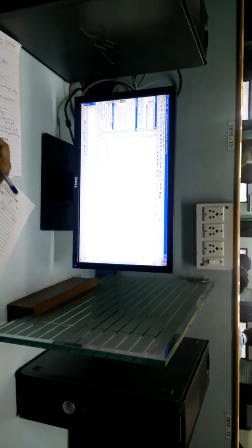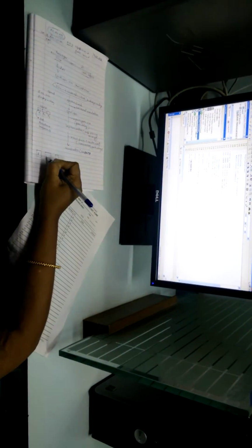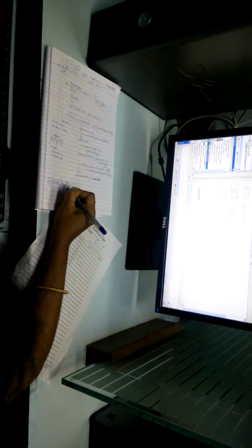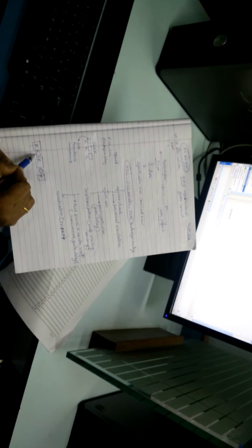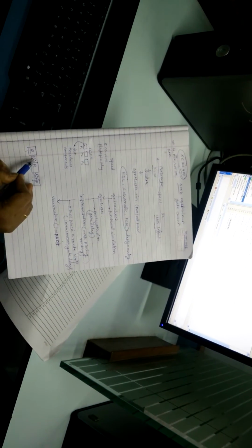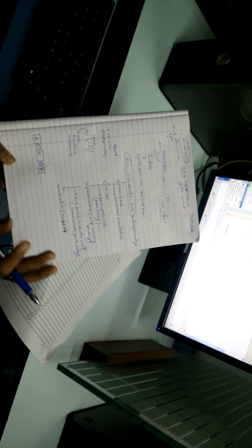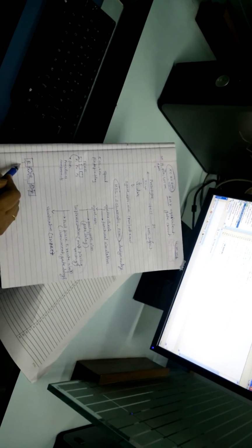Register transfer logic means any code is converted into registers with a combinational cloud in between. This cloud indicates a combinational circuit. This R is nothing but a flip-flop, the sequential part, and this is the combinational part. In case of a MUX, only the combinational part will be there, this R will be absent. A MUX is totally combinational, but in case of a shift register, you need both. The tool converts your code in this form. It is called RTL logic. So, RTL schematic.